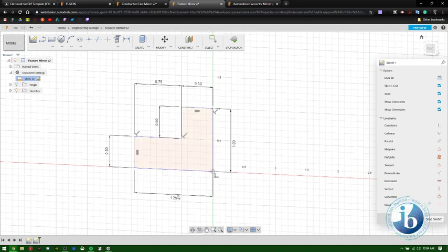I just kind of made these dimensions as I go. I drew a line, and before I pressed enter, I just punched in the number. You can also use this up here, which is you could draw it as the way it looks without any measurements, and then you can come back and draw with dimensions right here, and that's just kind of sketch dimensions that allow you to input them in after. So you pick whatever you want to do, doesn't matter.